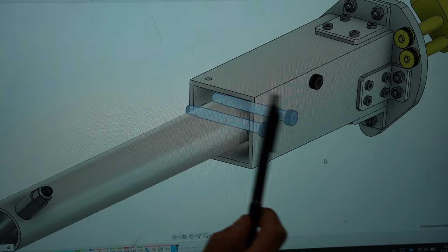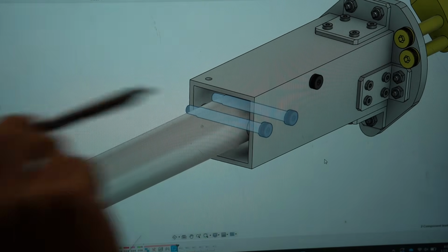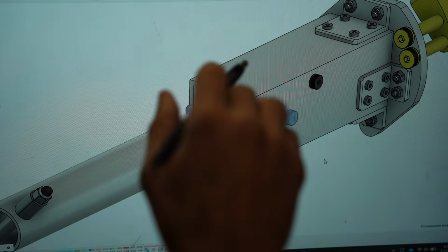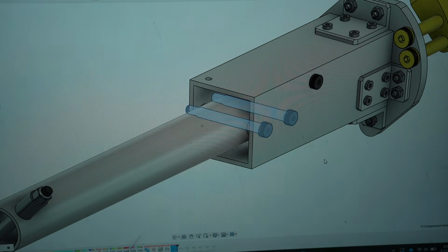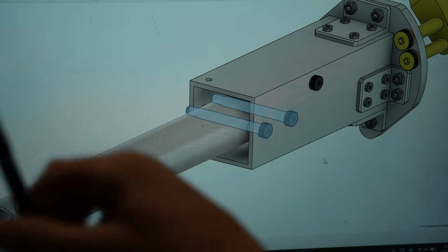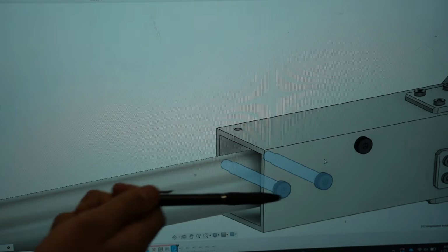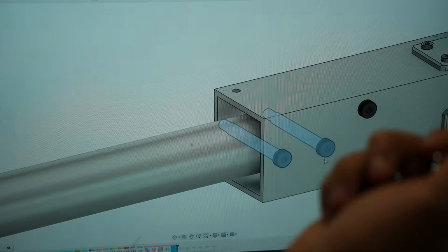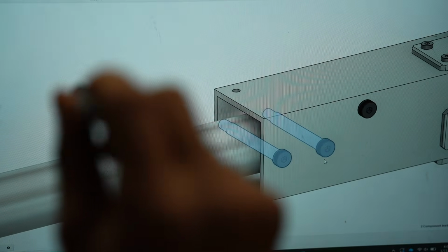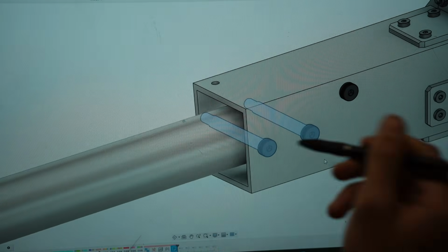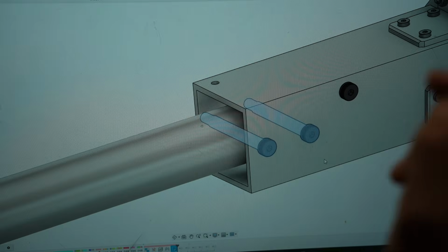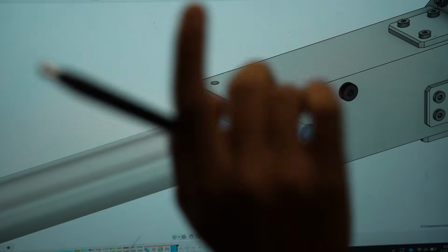The reason we use shoulder bolts instead of packing this gap is it's called design for analysis. Pins are much easier to analyze than a packed joint or even welds, really, and enable you to be very confident in your math.